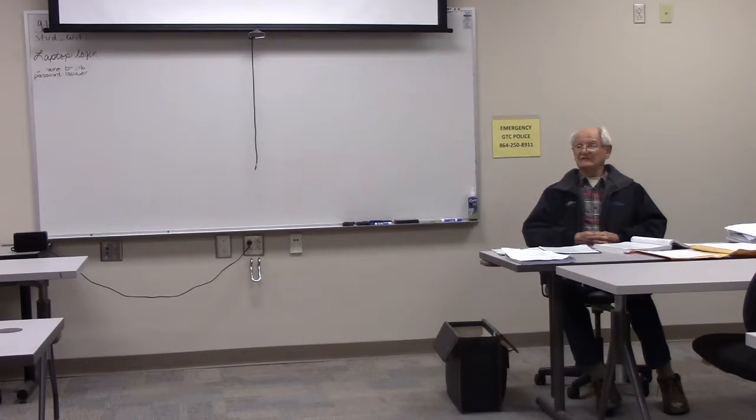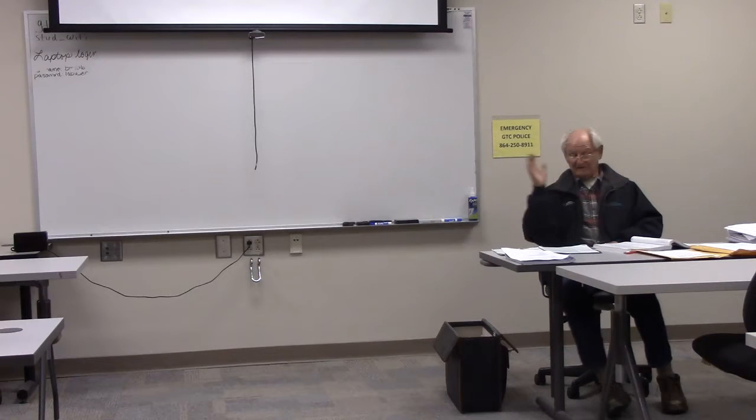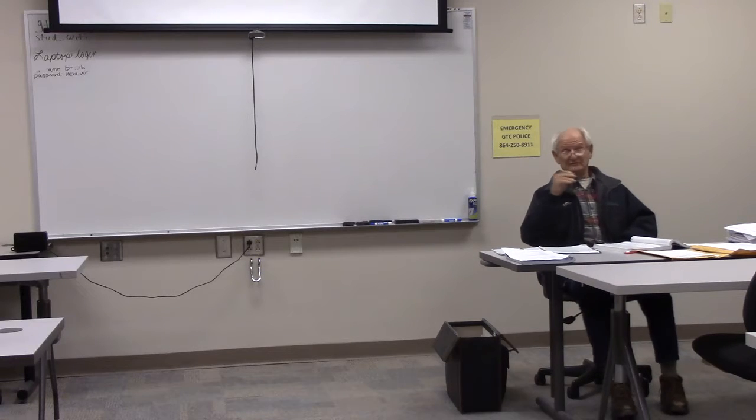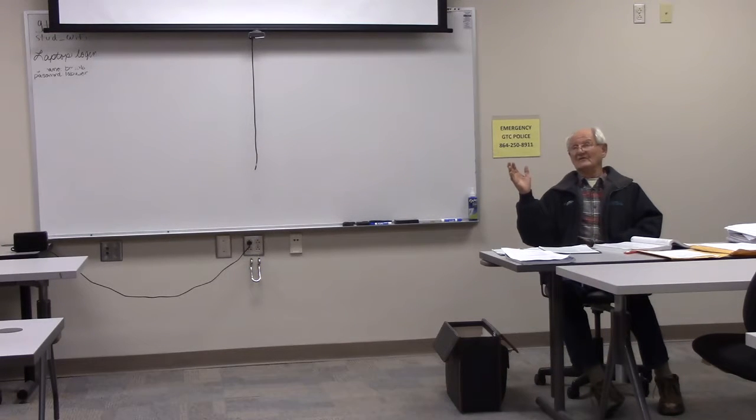So you don't have to count all the ground wires, you just count. If you got a ground in the box, it's one wire. Also remember that every metal box must be grounded. Say you had four conduits going into a box, and each conduit had a hot and a neutral and a ground wire.